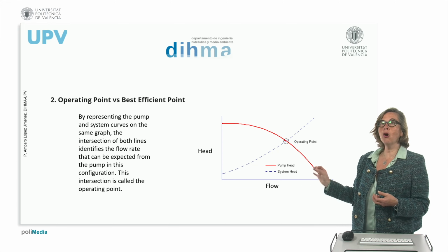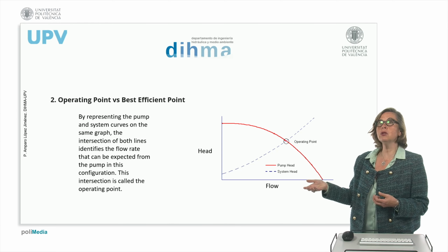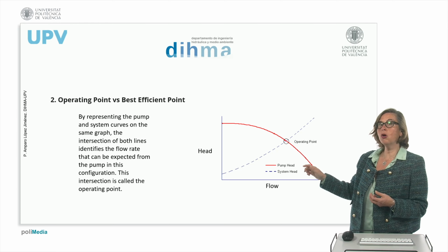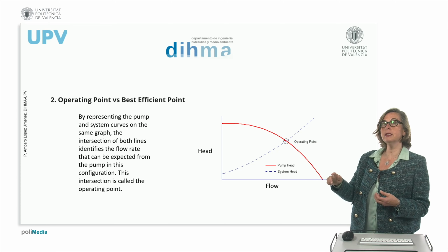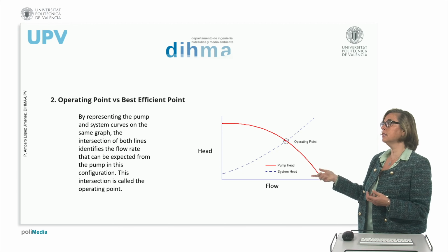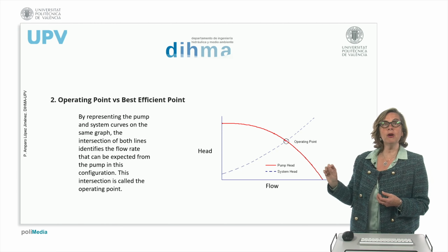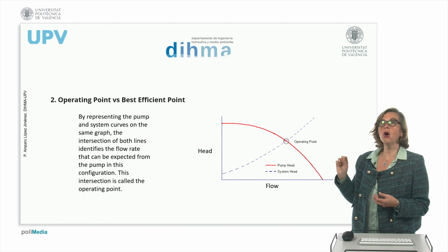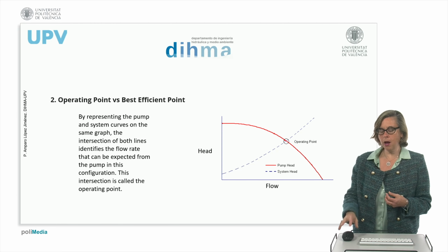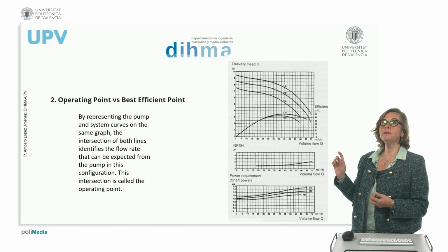In this case, the operation points relate the needs of the facility in which we install the pump, which has a head to pump and then all the losses in this parabolic increasing curve, and the main curve of the flow versus head, which we have here. The point in which they cross is the operating point. The operating point needs power related to the performance of the pump. So the operating point to be known needs the rest of the curves.